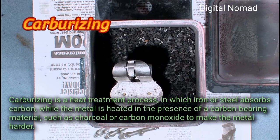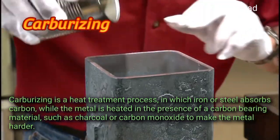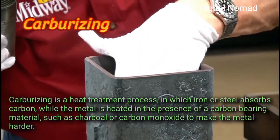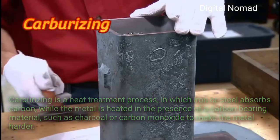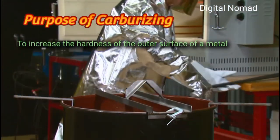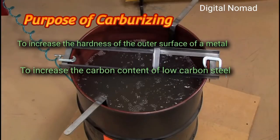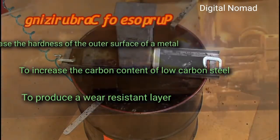Carburizing. Carburizing is a heat treatment process in which iron or steel absorbs carbon while the metal is heated in the presence of a carbon-bearing material, such as charcoal or carbon monoxide, to make the metal harder. Purpose of carburizing: to increase the hardness of the outer surface of a metal, to increase the carbon content of low-carbon steel, to produce a wear-resistant layer.